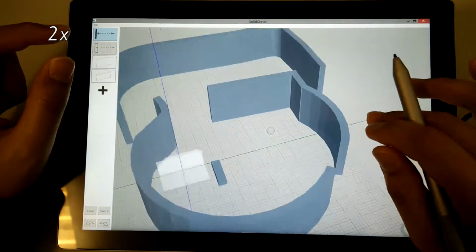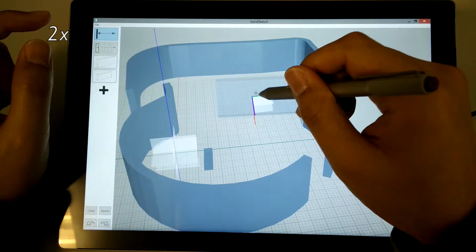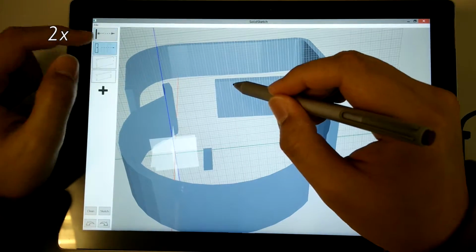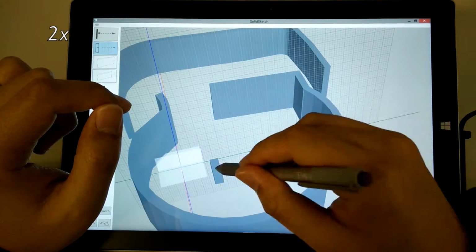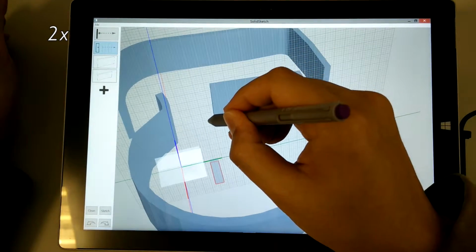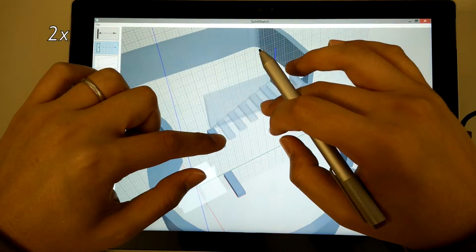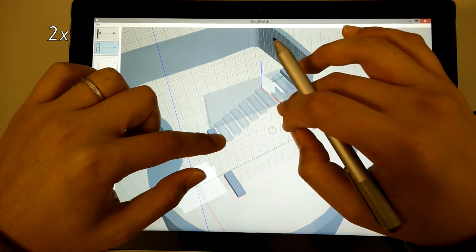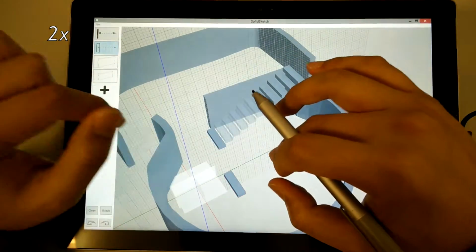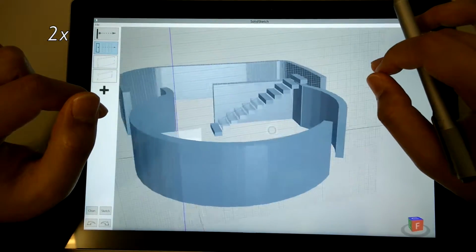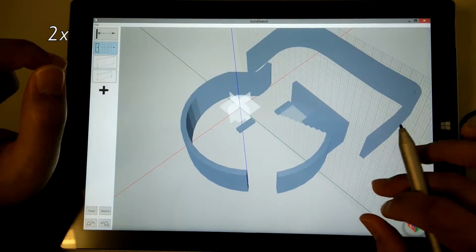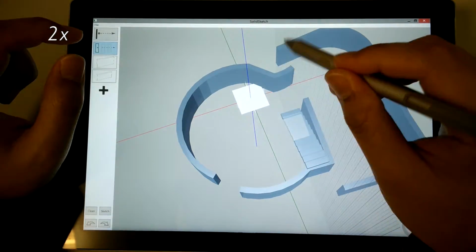To create a staircase, the user can perform a small lasso gesture to activate the Access widget, then tap the desired surface. Next, the user sketches a path while the Array template mode is selected. The system will generate a series of shapes along the path. To adjust the number of shapes in an array, the user can hold the first shape with one finger and move another finger closer to the first shape. The system will then add new shapes when there is enough room at the end of the path.